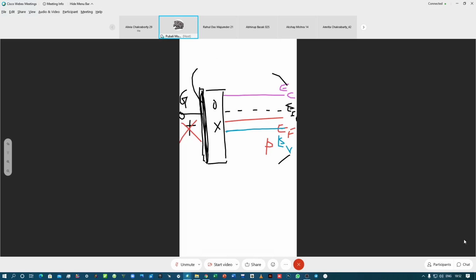Now, if we are applying this positive charge, which I erased, then what is going to happen? As we said, near the oxide semiconductor interface, there would be creation of a negative space charge region, or an induced space charge region with a negative charge. The minute this region near the interface becomes negatively charged, it has an excess of electrons, like the way we said that we are inducing the channel, so it is leading to the accumulation of negative charges over there.